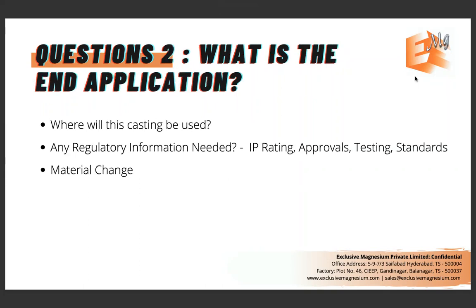Okay, what is the end application? Most manufacturers will not get into this, but it is a very valuable discussion to have with your manufacturer: where will the casting eventually be used, what is the actual use case? Once they understand that, they will be able to tell you what kind of regulatory information they would require. Like, is this supposed to be IP rated? Are there any approval standards? Is there any testing standards? Or is there any of those that come into play? So all those are important.